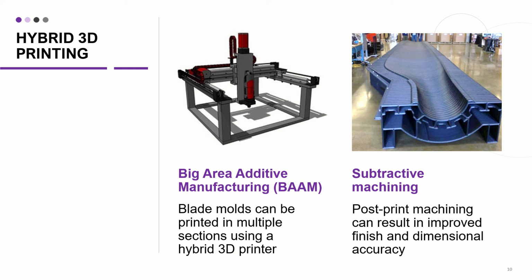A commercially available BAM unit can extrude 10 times as fast as a traditional 3D printer. Fiber-reinforced composites up to 6 meters in length can be directly printed. One limitation of BAM is part weakness in the Z direction due to sequential layer cooling. This constraint can be addressed by rotating the printed part to ensure that design loads are perpendicular to the Z